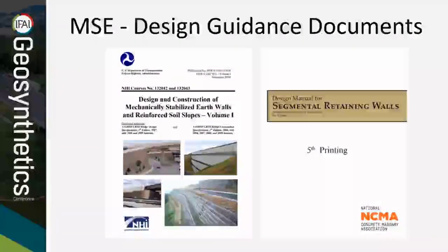Mechanically stabilized earth systems are a popular and economic option to construct retaining walls for highways or railways, wing walls and abutments for bridges, and numerous other applications for both public and private development. An MSE system is generally comprised of alternating layers of fill and reinforcement materials. These reinforcement materials are generally polymer-based, also known as geosynthetics, or they are made of steel.